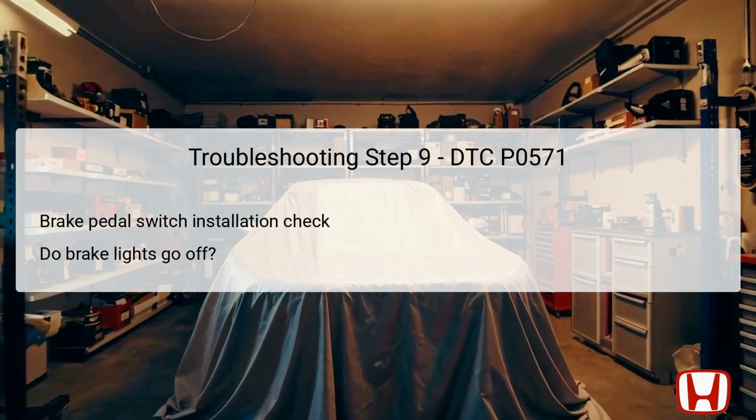In this step, the installation of the brake pedal position switch is examined to ensure proper engagement and adjustment. By removing the switch while keeping it connected, you will press its rod to see if the brake lights deactivate promptly. If the brake lights do not turn off when they should, this indicates an installation issue with the switch height or alignment, which may cause it to remain engaged unintentionally. Correcting the installation ensures that the switch can accurately reflect the position of the brake pedal at all times.